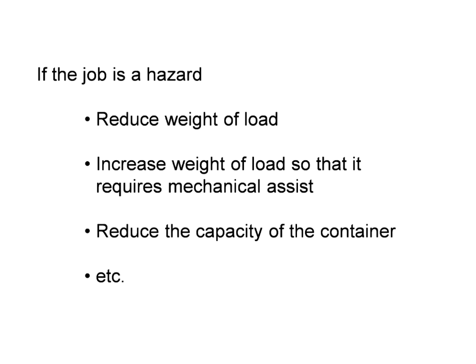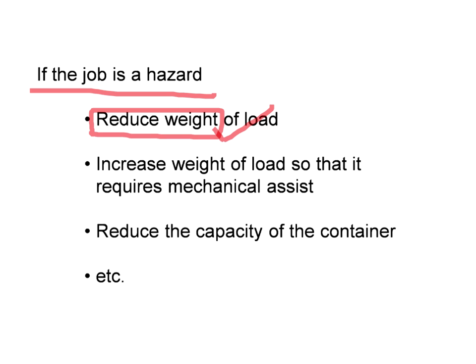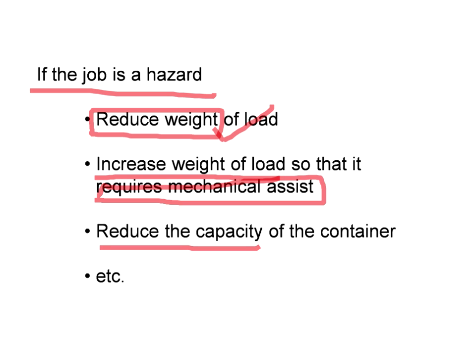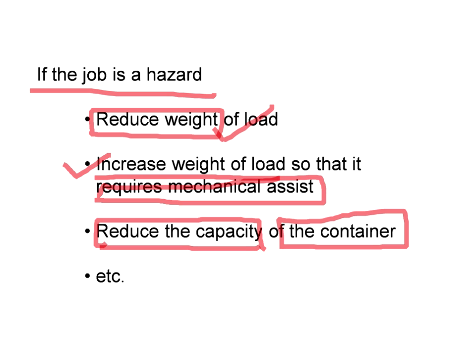If the lifting index, L divided by RWL, is greater than 1, it will lead to health hazards if carried by a human being, a laborer or a worker. Okay, fine. So if the job is a hazard, what to do?